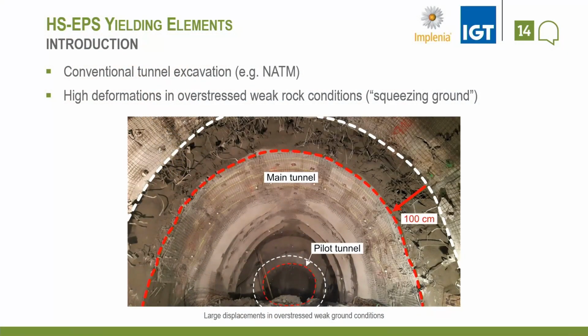When we talk about squeezing ground conditions, then we mean conventional tunnel excavation, for example, NATM. And this is always combined with large and often long-lasting displacements. So we are in a rock formation of very weak ground conditions and mostly with a high stress state.